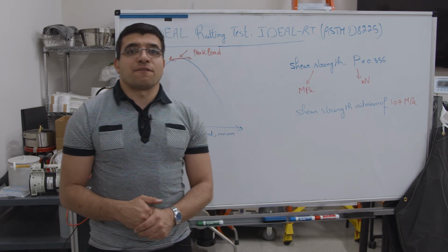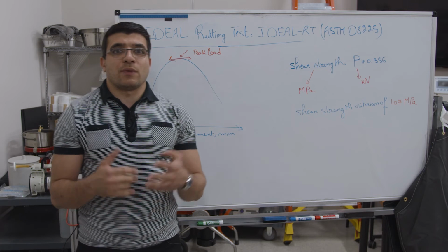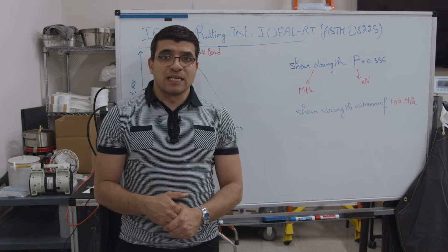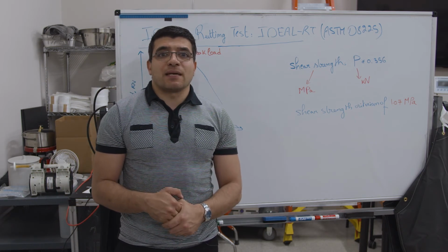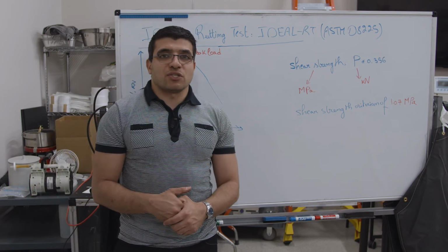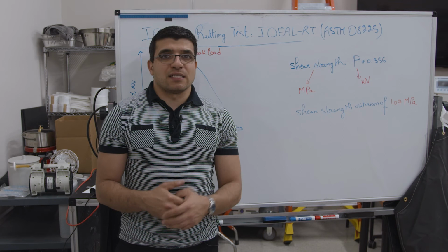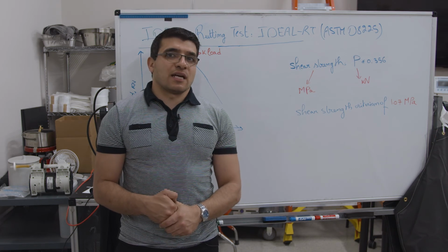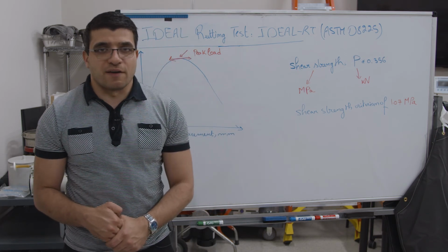In the case of field-produced mixtures, usually we minimize any potential cooling, and then we bring up the temperature of the mixtures to the design compaction temperature. Usually the mixture is compacted to the same thickness, same diameter, and a target air void of 7 plus or minus 0.5%.